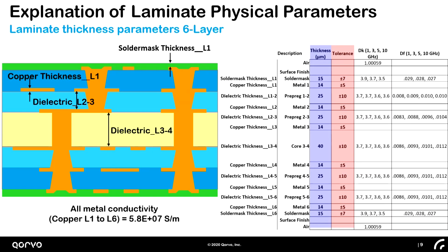So for those of you who have not seen laminates, basically, you've got these dielectric layers, you've got metal traces, you've got vias going between them. Call your attention to the thicknesses and the tolerances here. If you look, the metal thickness is like 14 microns. And you look over at this column, you see plus or minus 5, is that percent? No, that's actual values. So this is varying by plus or minus 50%. Okay, so that makes it really challenging. You have to know that.